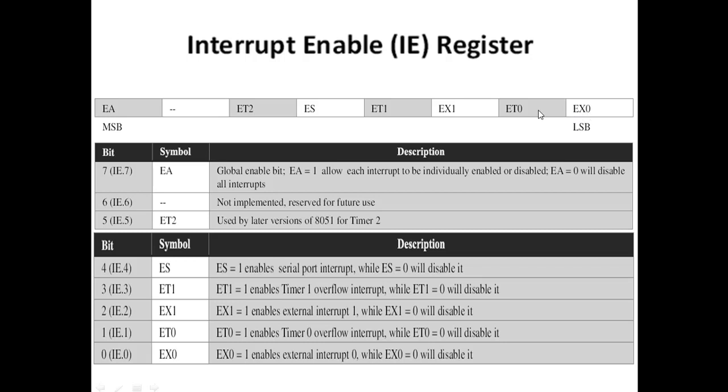So it becomes 0010 0001 if we read from MSB to LSB, that is 10000100. If we group them in hexadecimal, 1000 will be 8 and 0100 will be 4. So in hexadecimal it becomes 84.